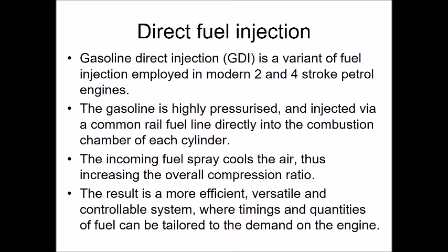So the incoming fuel spray goes into the chamber, and it actually cools the air. So the air's density changes, and it allows us to get a higher compression ratio. So we get better performance out of the overall engine. Might not make sense to you now, but it will do at the end of this part of the module.